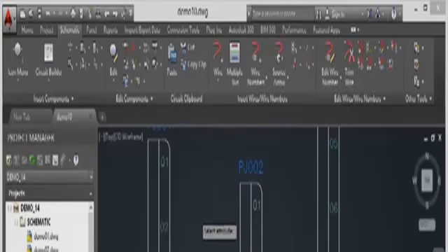If you want to do it via the ribbon, it's the schematic tab on the ribbon, the edit components panel, click on the flyout here, and you want edit selected attribute. So I use the pick box now. I'm going to select 01 there on PJ002, change that to A1 and click on OK. I might then select the second one and change that to A2. So I click on OK there. I can then press Enter or Escape just to finish off the command.